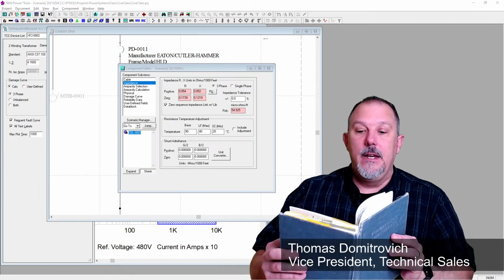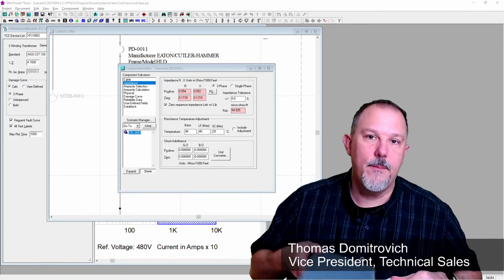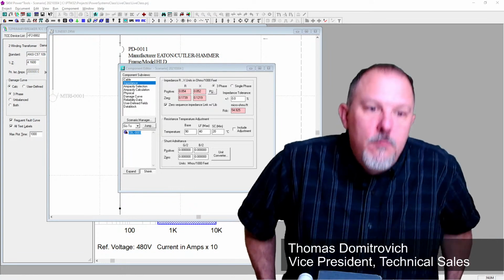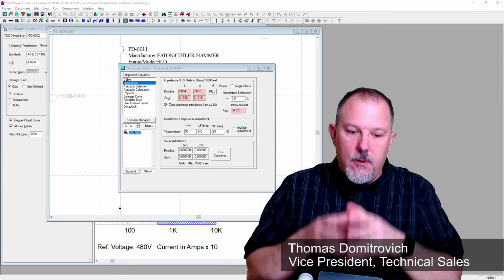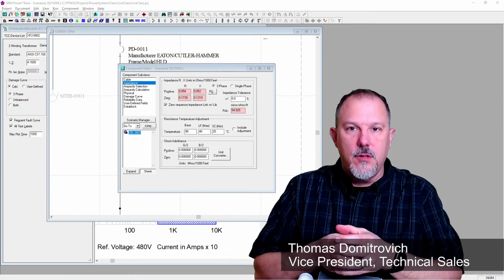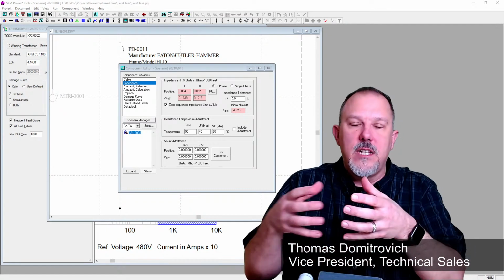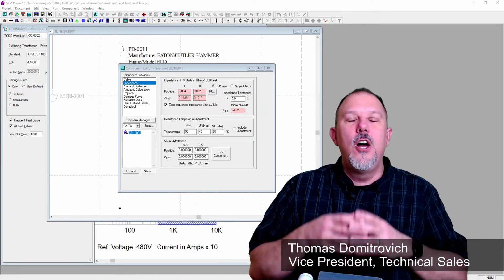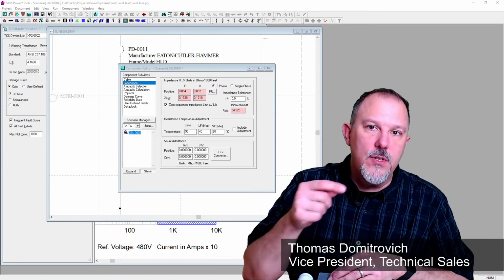Now, the conductors, I'm not going to look it up. It's complicated. The issue with conductors is that the zero sequence values of impedance are going to be dependent upon the diameters of those conductors, the proximity of the conductors with each other, and whether or not it's in a metallic raceway as opposed to a PVC raceway. So all of those factors come into play when you start talking zero sequence impedance.